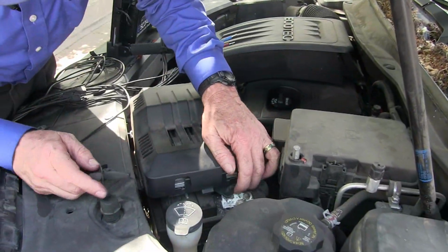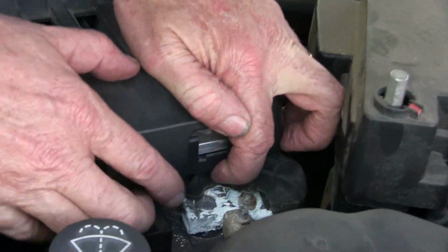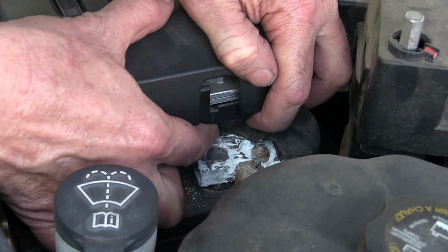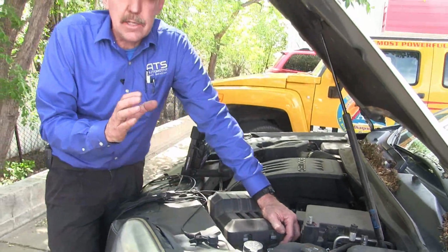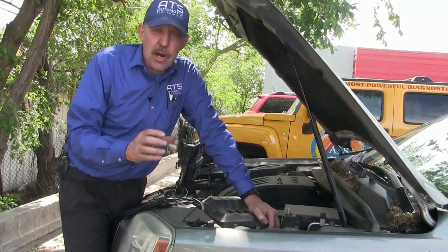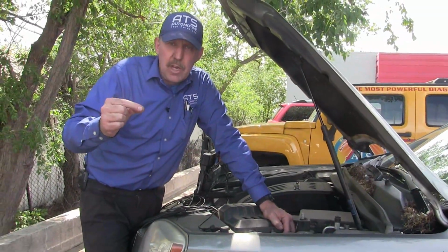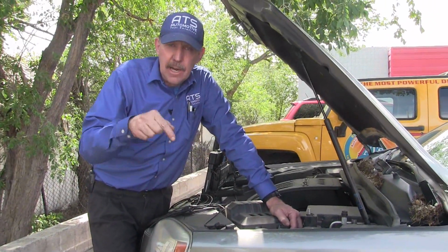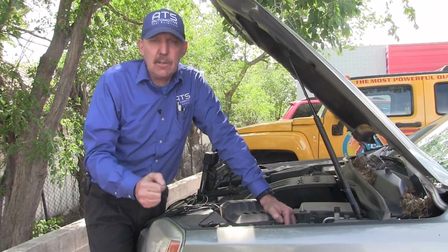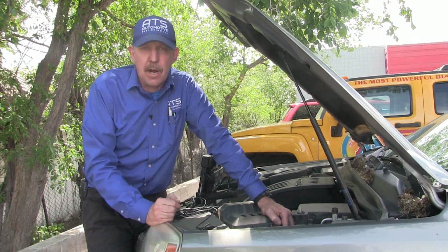Oh, wow. Okay, guys, I want you to look at this. Do you see how corroded this battery is? Now, that's a bad problem because I can't see a voltage drop. If I get on the outside of the post and it's got a lot of corrosion between the battery and the post, you can't see the voltage drop, and that could give me a problem.